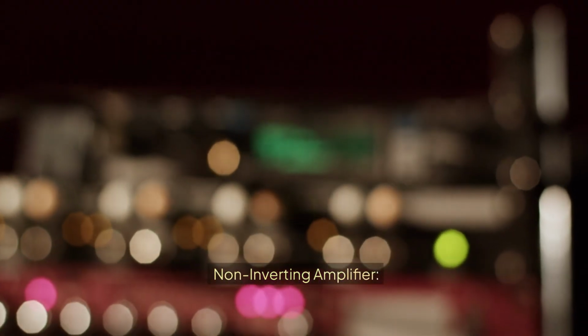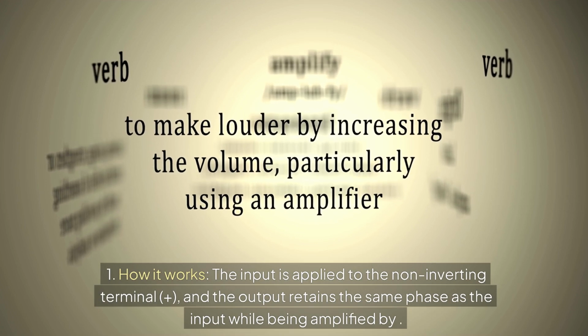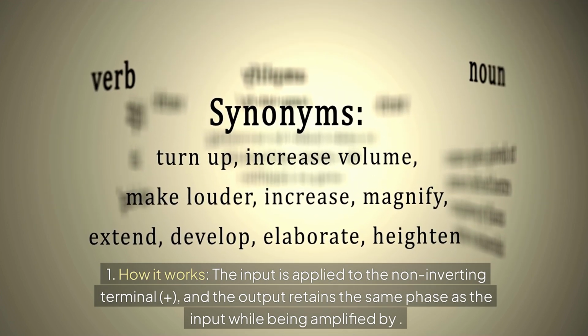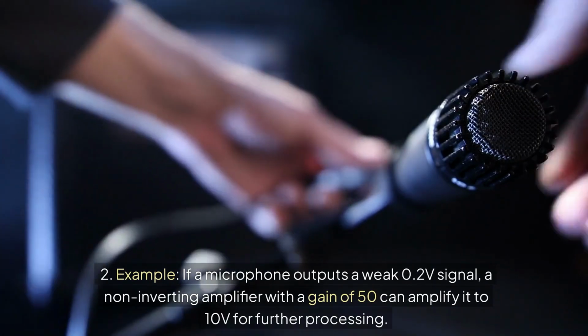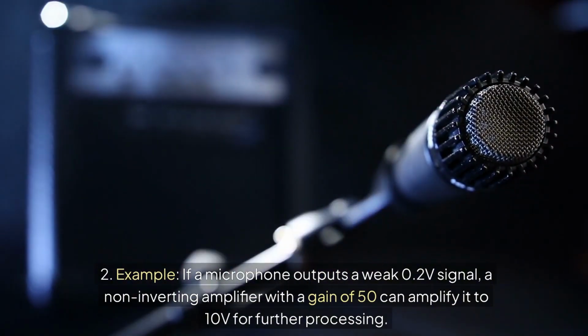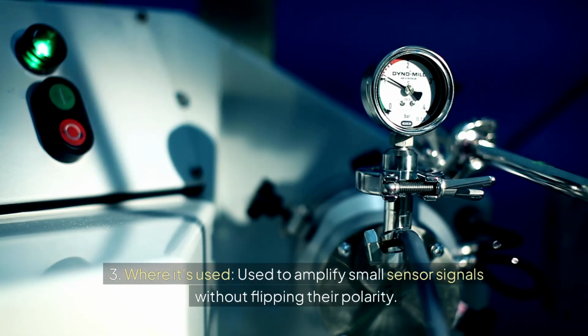Non-inverting amplifier. 1. How it works: the input is applied to the non-inverting terminal, plus, and the output retains the same phase as the input while being amplified. 2. Example: if a microphone outputs a weak 0.2V signal, a non-inverting amplifier with a gain of 50 can amplify it to 10V for further processing. 3. Where it's used: to amplify small sensor signals without flipping their polarity.